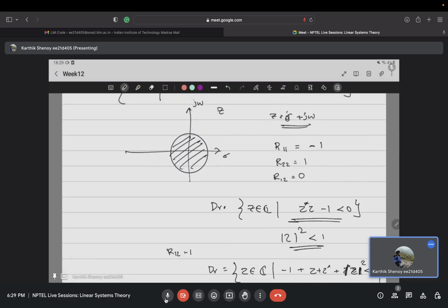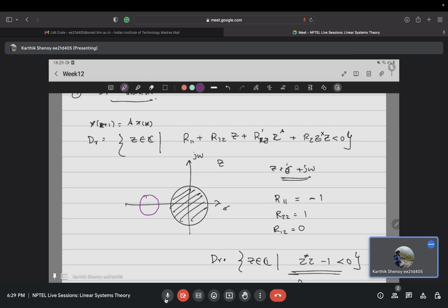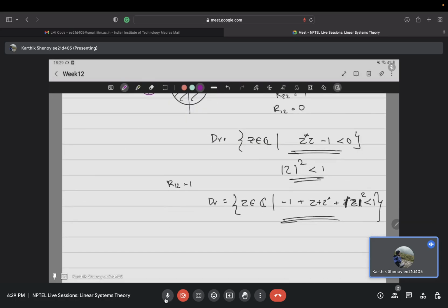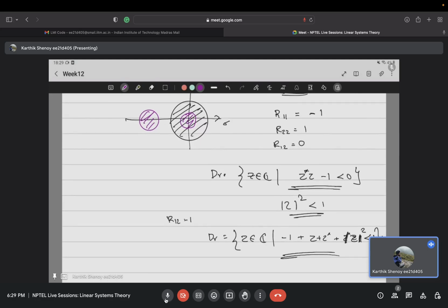Now, I can define regions like a circle here, a smaller circle here. So, what do these tell me? These are my locations for the eigenvalues. Depending on the performance that I need, if I am near the unit circle, then it is less stable or more oscillatory, and if I am closer to the origin, the response is faster and it decays faster.